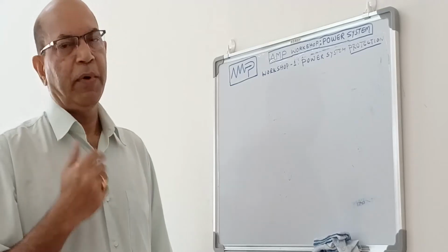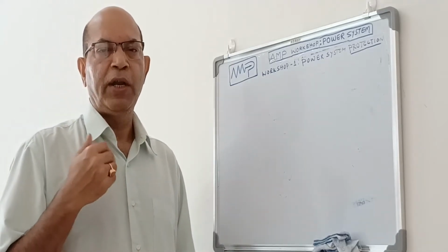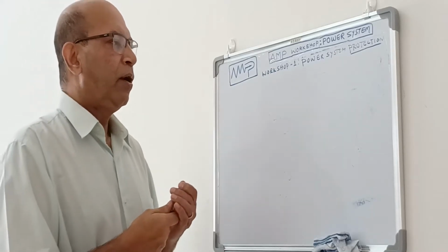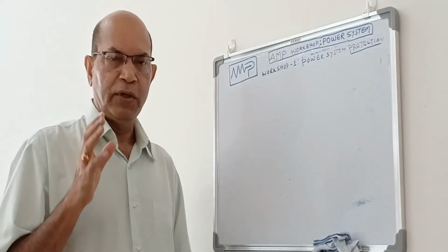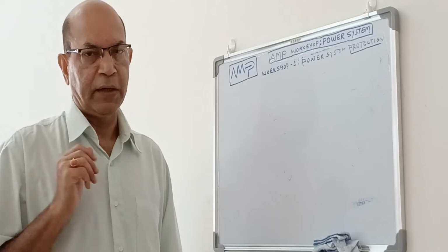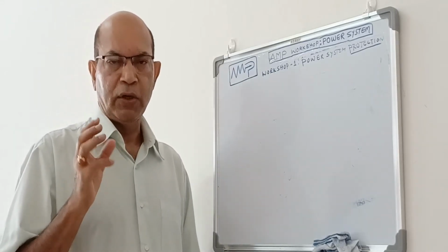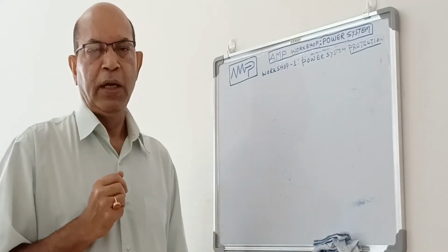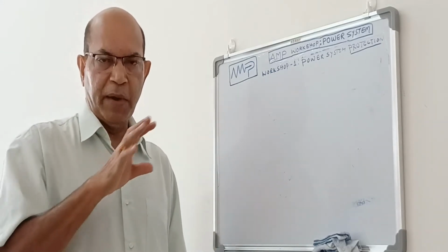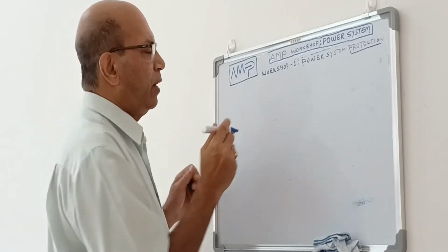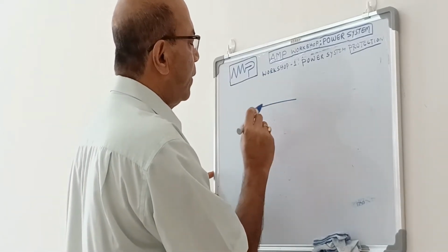Now there is another type of relay, which is called the electromagnetic disc type or induction type relay. The electromagnetic induction type relay does not work on DC; it works on AC supply only. The AC control supply given to the relay goes to a magnetic core over which the winding is wrapped. So I am drawing a schematic diagram of the relay. How does it work?